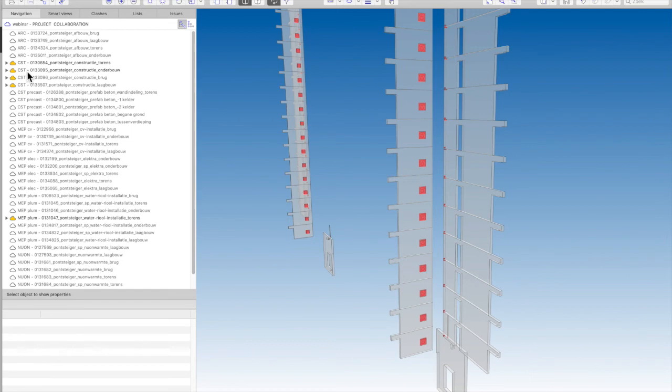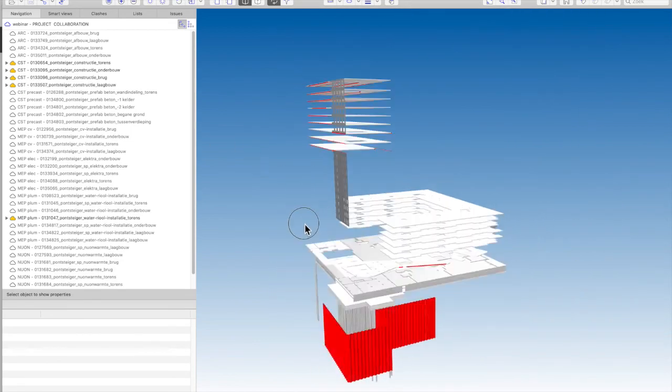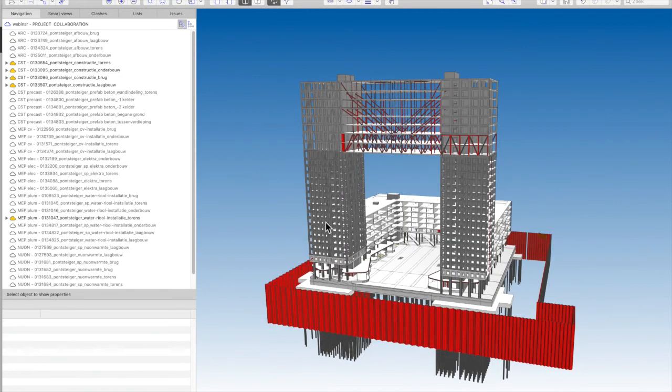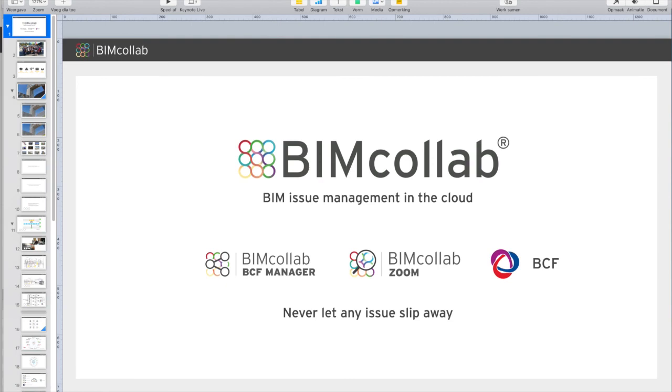And maybe some things which are tips here. I think the biggest tip I can give here is use the prefixes. So we know it is data management, and we have to tell the software where to look, which model, which name, or which component with which properties. And if you use a certain workflow for people to easily use it and say, just set a prefix on it, we can have a global understanding of the model quality. The BIM coordinator will have a lot of help from all the modelers, because they will send better IFC files, because they can use a tool that they do understand and can easily use.